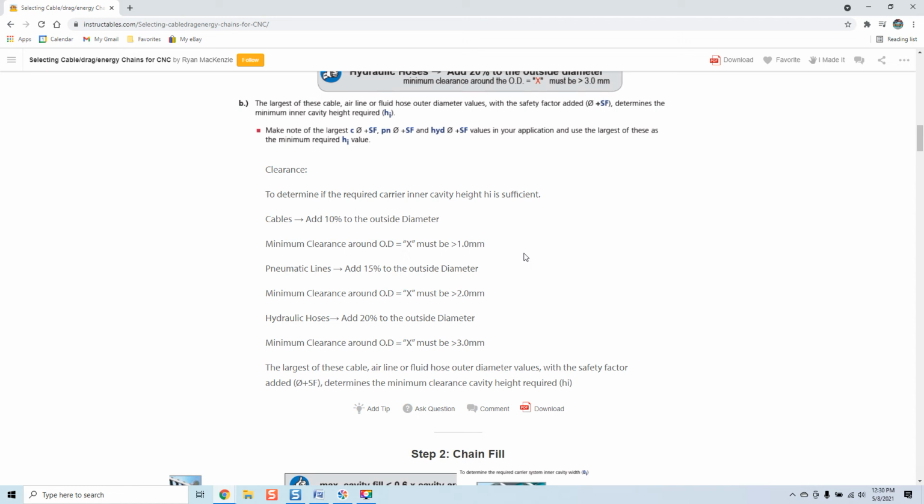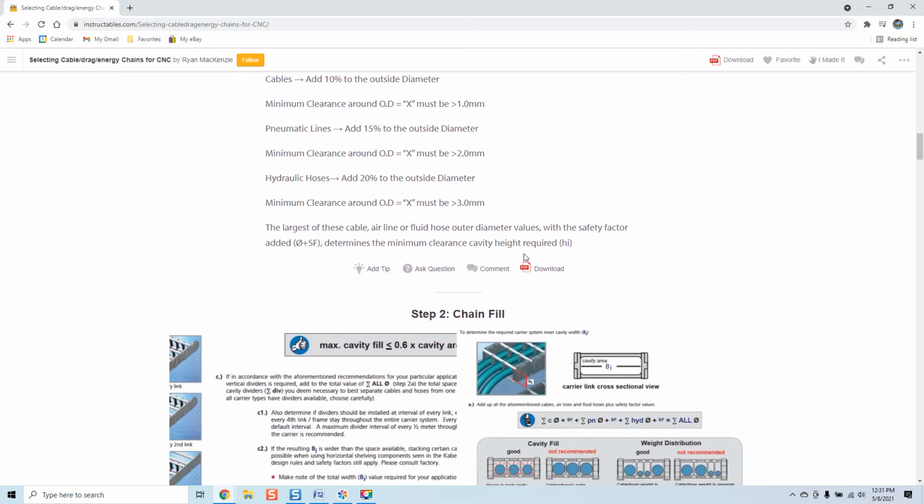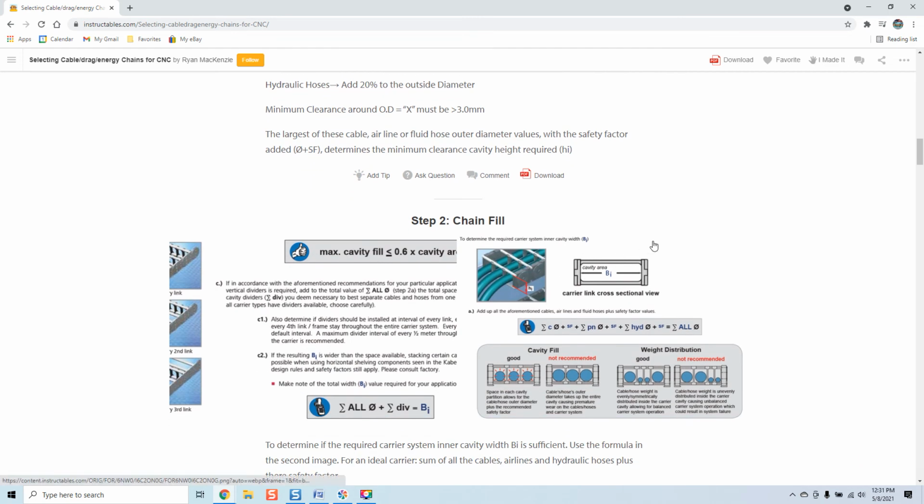If you put cables inside of a cable chain that has not been fitted properly, and you overload the cable chain, and we'll go into that, once again, we're going to pan through this actual article together, and you'll see what can happen and what many of you have experienced, may not even know you're experiencing currently. But if you do that, you can inadvertently create premature cable failure, all types of cable issues as far as signal disruption. And again, this article is imperative for those of you out there trying to do it right. And that's who I'm really focusing on.